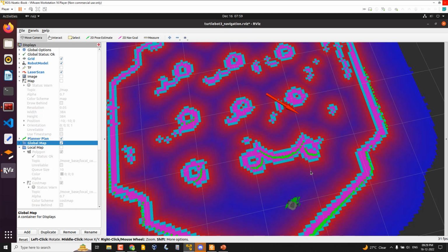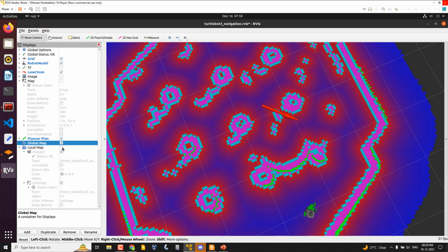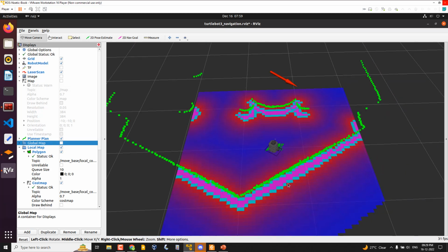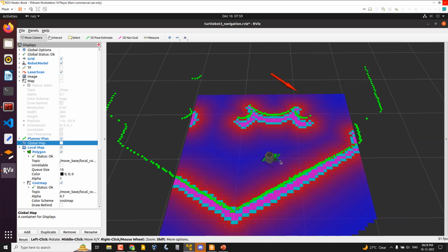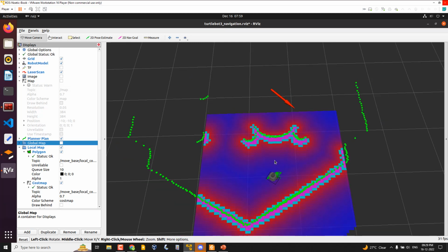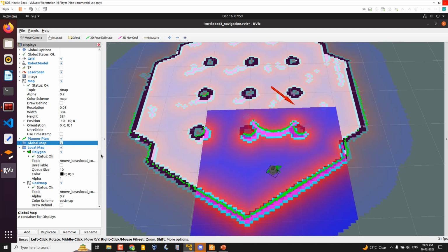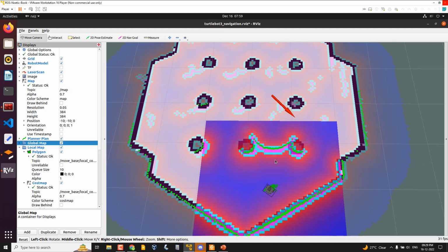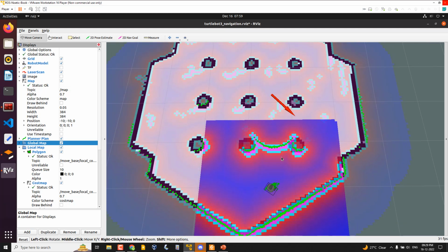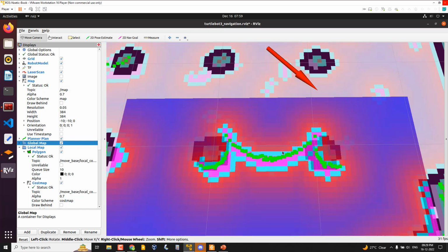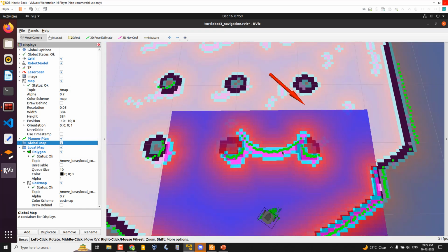Okay, so you can see here this is the global costmap, and the global costmap has that obstacle, and if you check the local costmap, it also has the obstacle. So instead of taking the whole map, it is actually considering these sections. Maybe I can come to the point. This is how the global and local costmaps help the planners to avoid the path, I mean, if there is an obstacle.